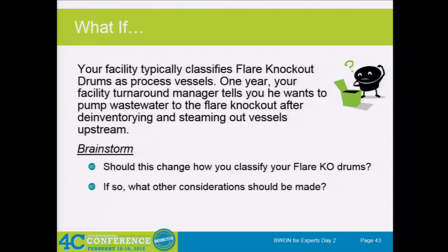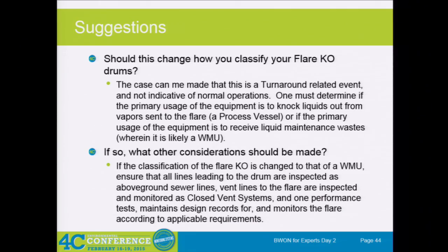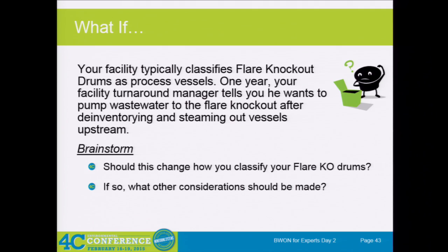And what other considerations would have to be made if you bring your flare knockout drum into the BWON program as a waste management unit? Again, you've probably brought your refinery flare into your BWON program as a control device, which brings in a lot of extra piping for inspection and monitoring. I'm so confused by that. You're bringing in the flare. Why are you monitoring everything on the flare?